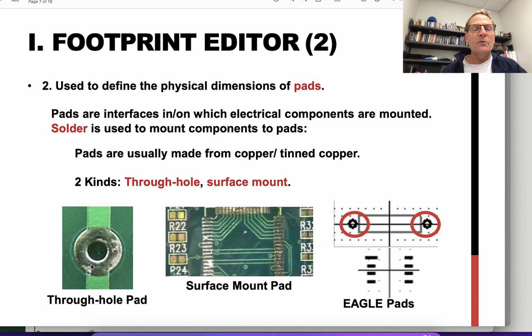It is done through through-hole pads in certain cases, and in surface mount component cases, which we'll talk about later in the lecture, we have a surface pad, no hole, but just a pad where the component will sit atop the board and be soldered on in a different way that we'll talk about. But each has a footprint, whether it be a pad for the surface mount components or holes for through-hole mounted components. Each is represented, and they must be captured by the software and be able to be communicated through the software design.